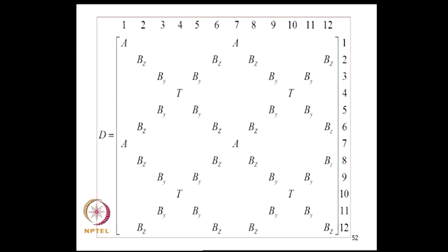So for a built up structure such as the 2 examples that we considered, for each of the elements we again formulate the dynamic stiffness matrix. The coordinate transformation rules are exactly the same as have been used for static problems, and the reduced equation now will be an algebraic equation. So that can be inverted for every omega to get the required frequency response functions.